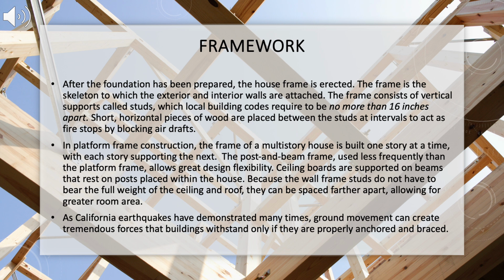The post and beam frame, used less frequently than the platform frame, allows great design flexibility. Ceiling boards are supported on beams that rest on posts placed within the house. Because the wall frame studs do not have to bear the full weight of the ceiling and roof, they can be spaced farther apart, allowing for greater room area.